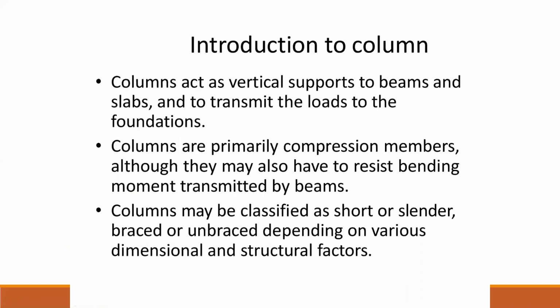The introduction to the columns. Columns act as vertical supports to the beams and the slabs and transmit the loads to the foundation. As you know, the load point is created through the slab. The slabs will be loaded and those loads will be transferred to the primary and the secondary beams around that. Then after that, all these loads will be transferred to the columns, which support the foundation. So these are the primary elements that we are supposed to design in today's session.